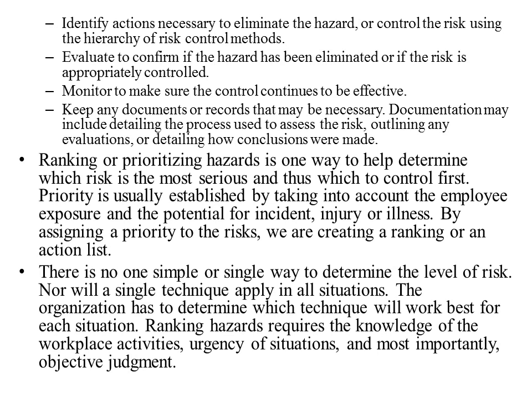These places are all enclosed, and whenever we have an enclosed space, there are chances that the supply of air will be inadequate because the space is very small, or it is likely to be reduced to inadequate for sustaining life. For a short period we can stay in a confined space, but not long enough. There is a risk of engulfment by the material.